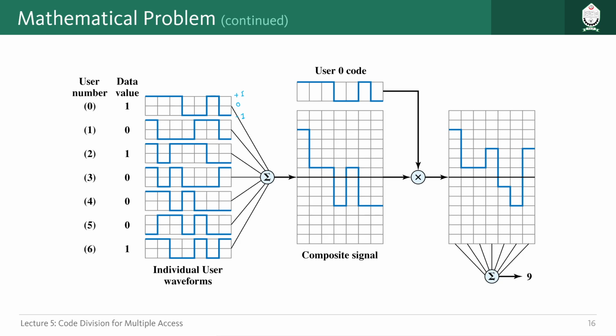As a result, what will happen? At the channel, all of this signal will get combined, right? This is the combined or composite signal we are seeing, and here this is the reference or zero level. If we add all of them up, that will result in a value like this. You see, this can be shown actually. This is 1, 2, 3, 4, 5. This is -1. So 5 minus 1 is equal to 4. Again +1, so 5. So total +5 should be for the first time slot.